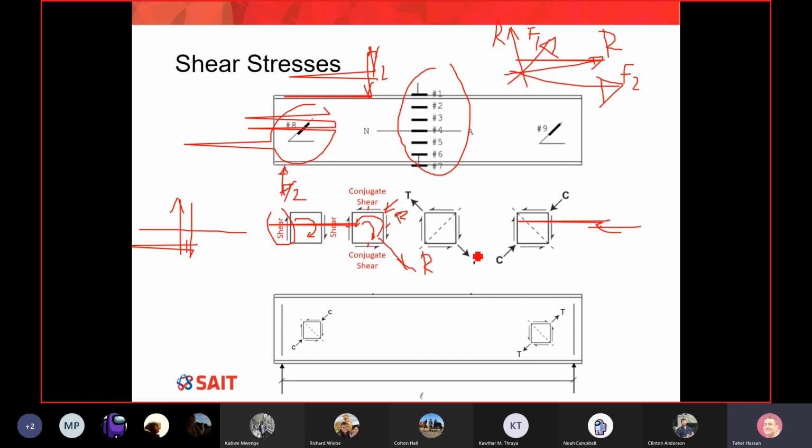Two orthogonal. I'm showing you in sketch number 3, this one here, the direction of the T or the tension, and this one the direction of the C. So really it depends on the direction of my strain gauge. If I orient my strain gauge this way, what do we measure, tension or compression? If I orient my strain gauge this way, what does it measure? Tension. How about if I orient my strain gauge this way? What does it measure? Compression.